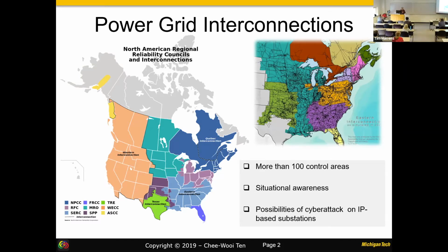So basically, power is lost as it transfers from one location to the other. So what we do is we step up the voltage as high as possible. As a result, the current will proportionally reduce, and as a result, the loss of power can be minimal. So you increase the voltage, the current gets smaller, and then eventually the power gets to us as you step down to the distribution system, and then eventually residential, and then our outlet here.